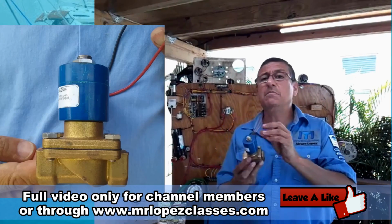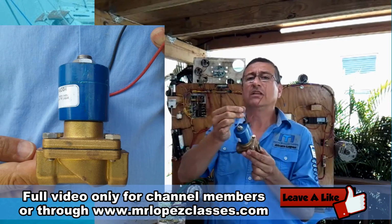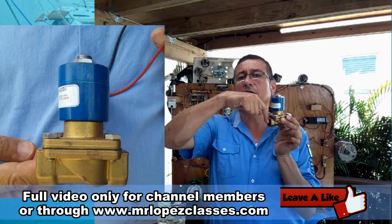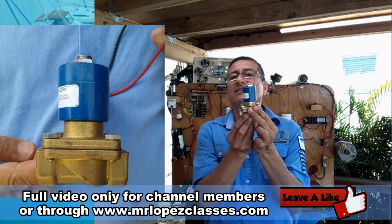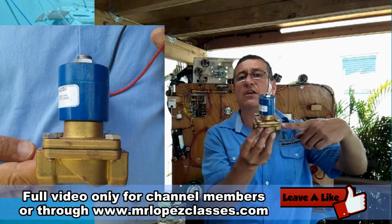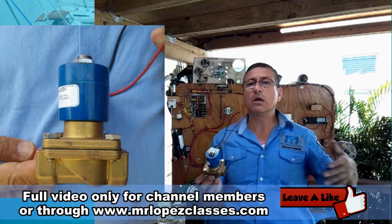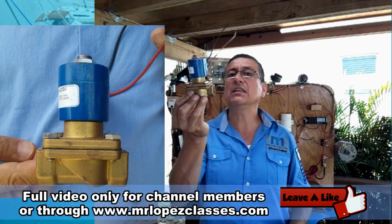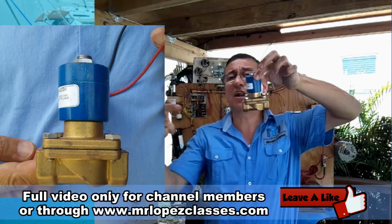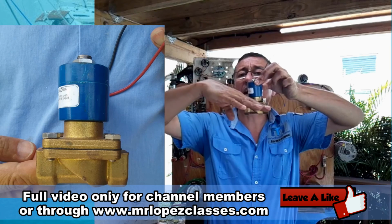Solenoids can be used in other types of application like this. This is a solenoid. When the solenoid is powered, positive and negative, immediately the plunger closes the valve. This is a solenoid valve to control the movement of fluid. What type of fluid? Water, gasoline, diesel, gas, alcohol, any type of fluid. The fluid can be controlled. The fluid enters here and continues over there. You see the shape of that valve.